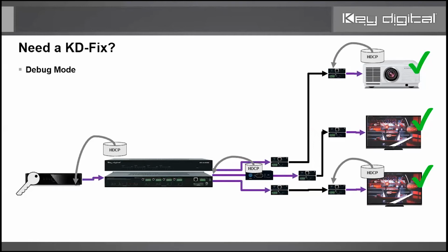How are we doing that? Because we are, in fact, HDCP compliant, and we have HDCP licensing on every input and output connection of our product. And therefore, we are checking HDCP when needed, and we are able to provide that. And if there's that electrical interference down line, we are still sending that signal through because we are checking HDCP when that line is healthy.